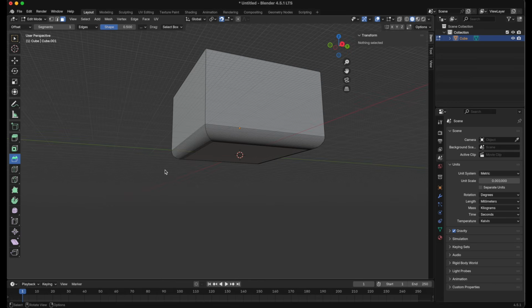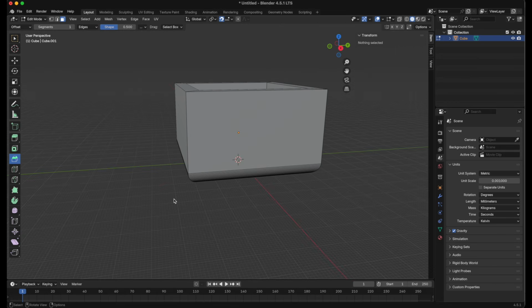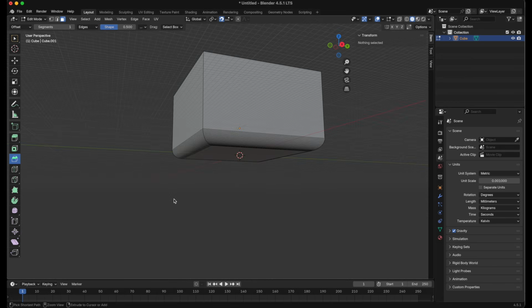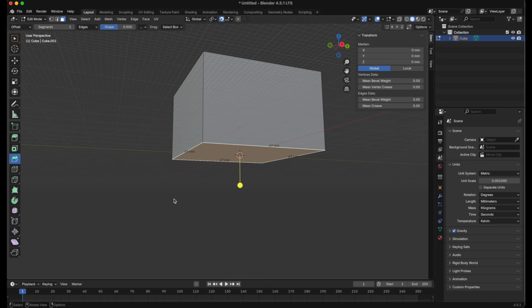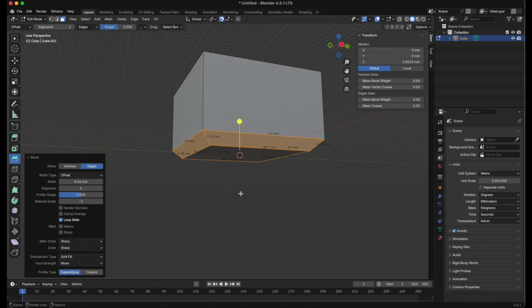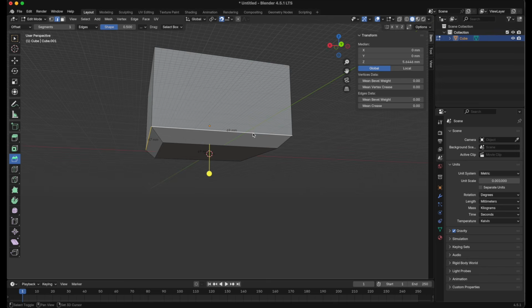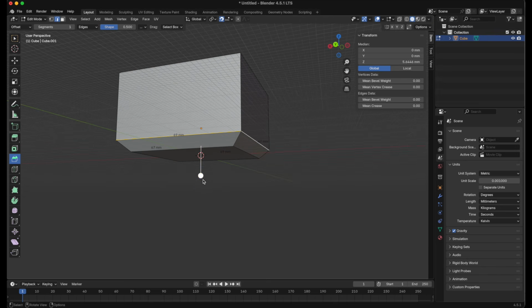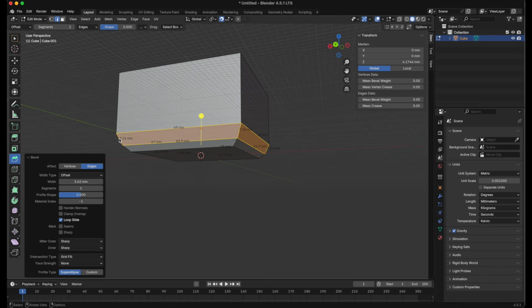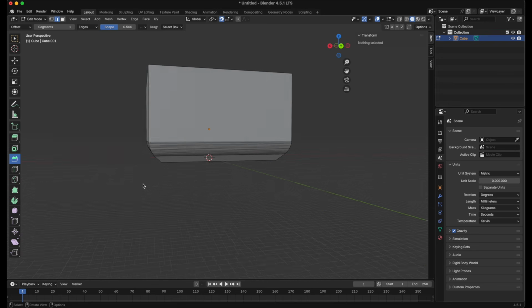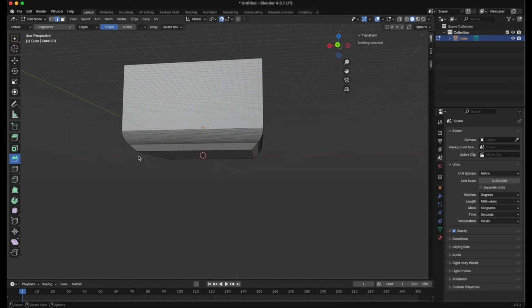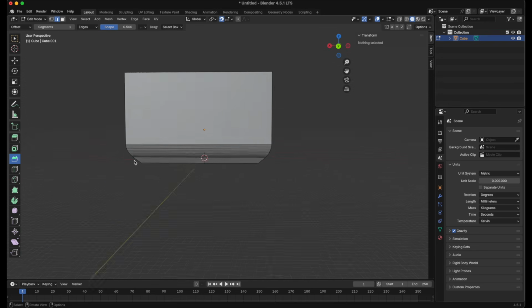A clever way to add a rounded edge to the bottom of an object for designing for 3D printing is to add a combo of a chamfer and a fillet. So let's go ahead and drag the bevel like so. Okay, that looks good. Now let's go into edge selection mode and we'll select only these top edges here, like so. Now when we drag it, you'll see we're adding another bevel. But let's go ahead and add more segments here to make it rounded. We'll add 20. So now what we've done is we've created a hybrid of a chamfer and a fillet, and it only has a 45 degree, so it is printable.